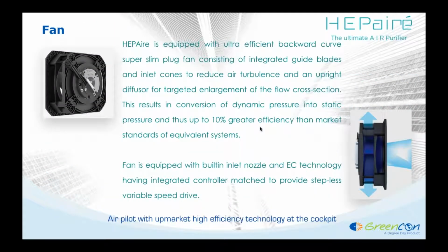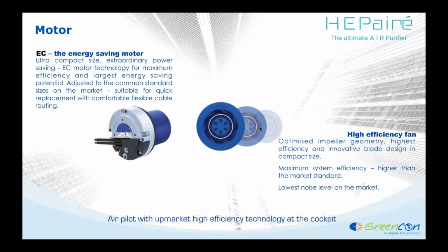Very simple. The thing does not need to be very complicated. We have not done any great engineering. We have just utilized the basic fundamentals of sizing the fan, utilizing the fan laws, and utilizing the pressure drops of various kinds of filters which are available. This unit comprises one of the world's most advanced EC fans, which is a plug fan, so there are no maintenance points. It has a life of more than 50,000 hours and works almost continuously without the need of any mechanical intervention or failure.